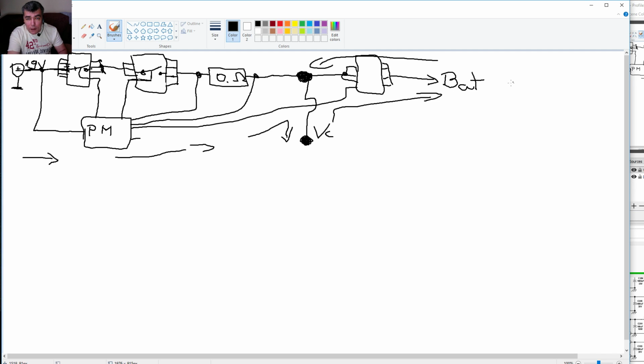And the battery, let's say you have a 4 cell battery. 4 cells means 3.6 is the lowest, times 4, 14.4. Probably you don't have that. You have 3 elements. So you have 3.6 volts lithium elements times 3, 10.8. 10.8 means discharged, like 0%, and fully charged is 4.2 times 3 equals 12.6.